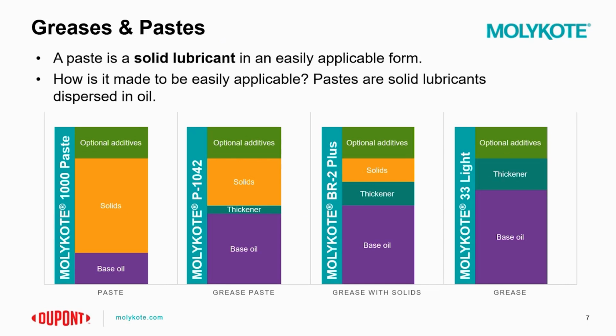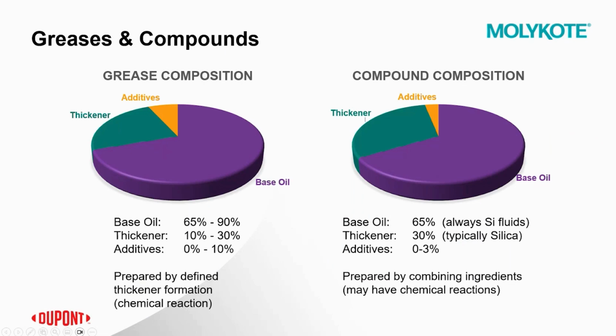And the amount of solid lubricant in the formulation also varies. So you could have a very high percentage of solid lubricants in the oil and form a very tacky, grease-like paste. And overall, the choice of additives within the formulation is very much application dependent. So again, you could select additives for corrosion protection, to increase the tackiness of a formula, or even to thicken the material overall. So now we could look at additives in compound technologies.